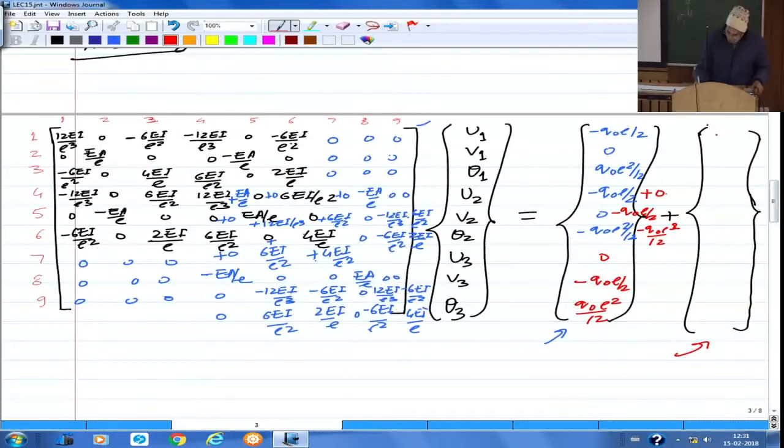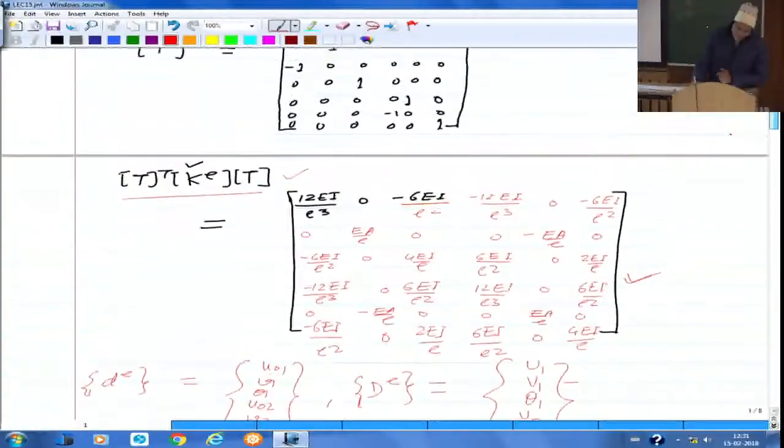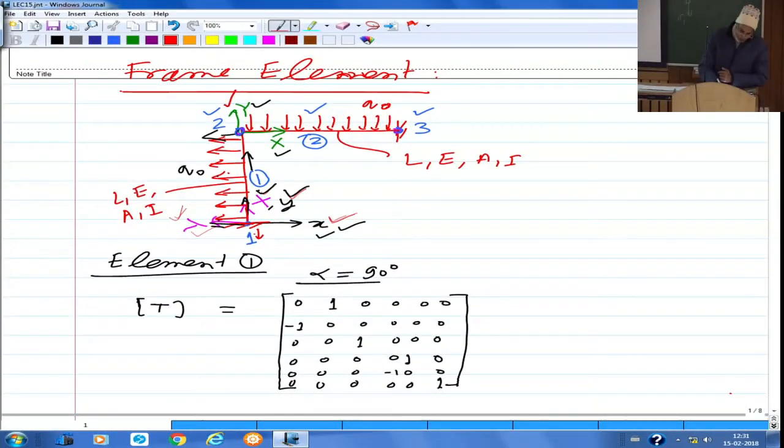So I can take this force here as my first node first element, so Fx first node first element, then minus F, where I am putting subscript small xy, meaning the forces along global xy direction. So first node first element, and the moment is, let us say, first node first element. This is the contribution from the first node. Then for the second node, the outward normal is along positive y direction here, so the positive forces are going to be along positive coordinate direction.